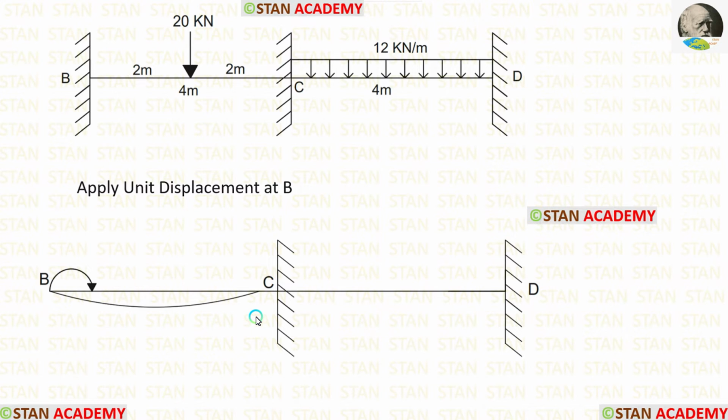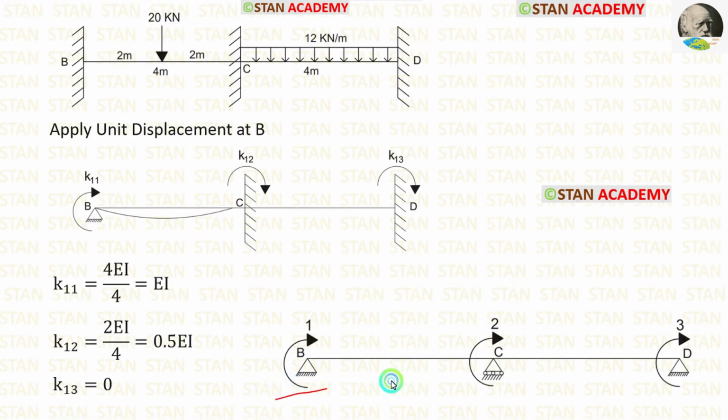We have to give some gap between the fixed support and the curve because in the fixed support there will be no slope. You can see that I have given some gap between the fixed support and the curve. That is why the curve ends before the point C and can't continue after the point C. Same like here, the ordinates should be made in the clockwise direction.